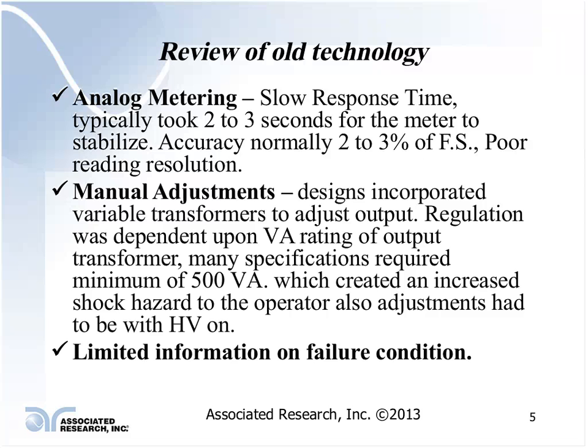So, some of the older testers, or even some of the standards that require a 500 VA rated tester, are rather questionable in regards to safety of the operator. If the Hipot you're using has a regulated output, then you can get by with a tester that has a much lower current capacity, provided it has the capacity to test your product.